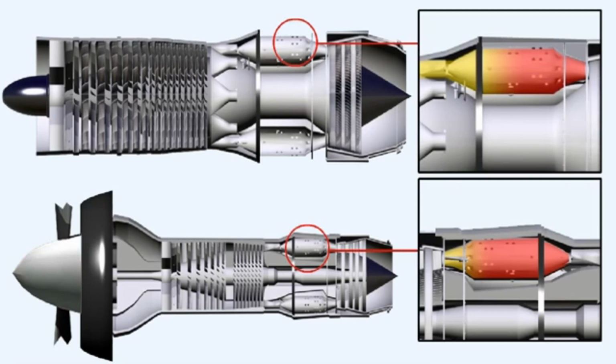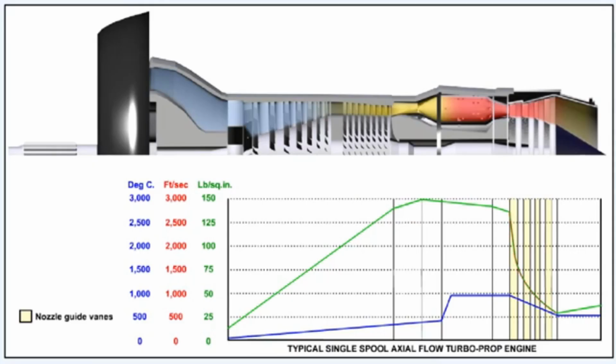Apart from this difference, the airflow through the engines is virtually the same in either case. The compressor passes the air to the combustion chambers where the fuel is added and the mixture is burnt, and because of the temperature rise, a substantial increase in the volume of the air is obtained at a nominally constant pressure. The gas is now expanded in the turbines, where a drop in the pressure